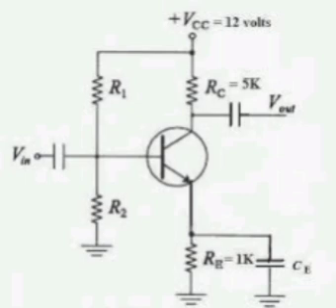R equivalent on the LV side equals 2.4 by 10 squared plus 0.03 ohms, that equals 0.054 ohms. X equivalent on the LV side equals 6 by 10 squared plus 0.07 ohms, that equals 0.13 ohms. Load equals 5 plus j3.5 ohms, that equals 6.10 at an angle of 35 degrees. I2 equals Vt by ZL, Vt by 6.10.